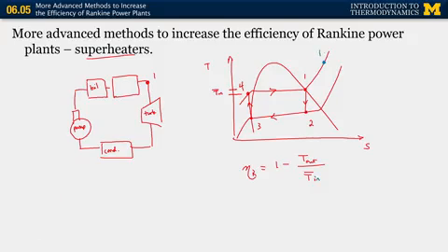If I take that power plant and say, I want to move this exit state out here, let's call that one superheat, okay, and this is just one boiler with just the boiler. I'm going to address two issues simultaneously. I'm going to get that turbine so that it's only operating on a vapor, and I'm going to increase the temperature at which I'm adding heat. So we can see that here. So again, I'm going to isentropically expand through my turbine. So now this is to the exit state of the superheated steam.